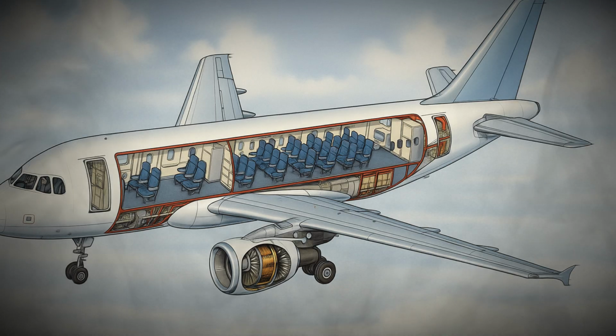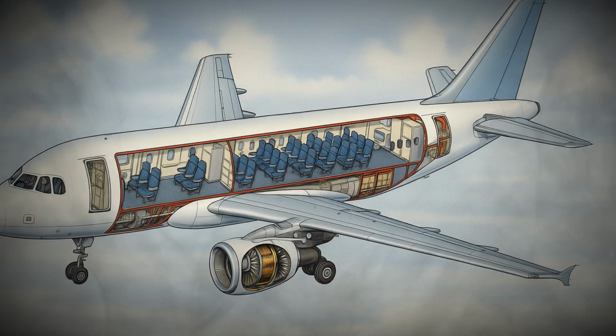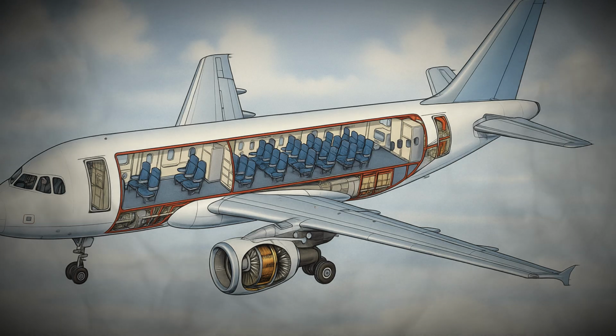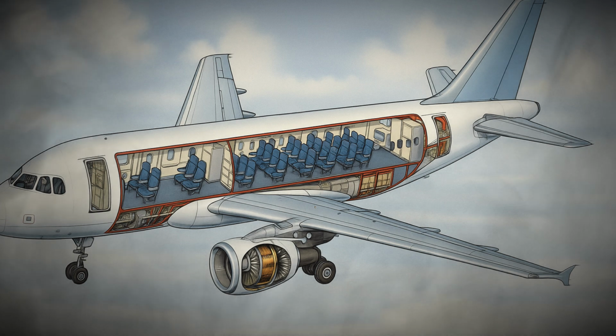Fire safety is addressed with built-in extinguishing systems for engines, cargo holds, and auxiliary power units. Smoke detectors monitor enclosed spaces, and pilots have immediate access to fire suppression equipment. Fuel tanks are designed with inerting systems that reduce the risk of explosion, using nitrogen-enriched air to displace oxygen in empty spaces. Cabin safety systems focus on passenger survival in emergencies.